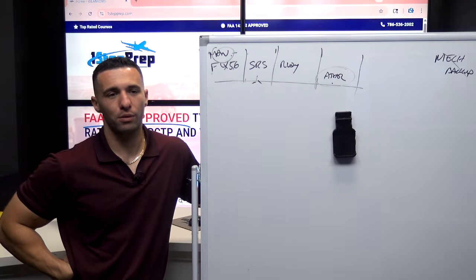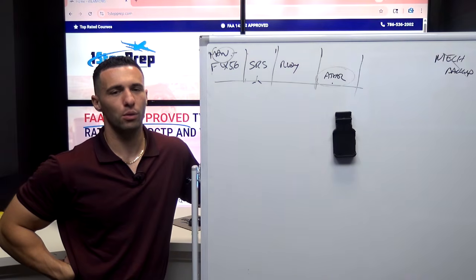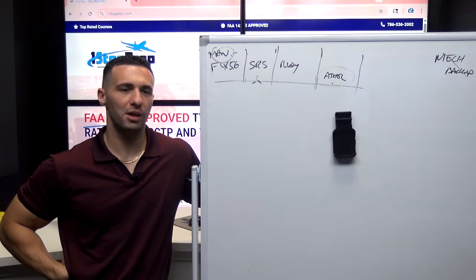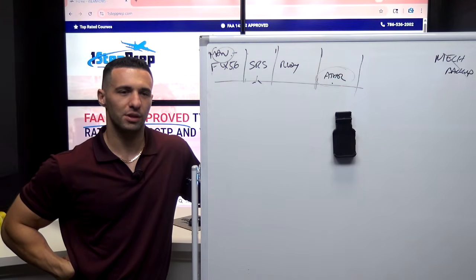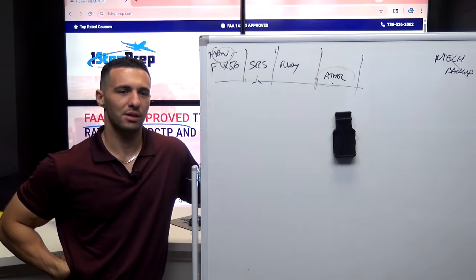US Air had a rudder hard over in the 737. I don't know if it was related to the yaw damper, but they definitely had a rudder hard over. And differential thrust is your friend in that case. On the flight control page, it might display it. I'm not sure. I'd have to look at that, but that's what I would expect.